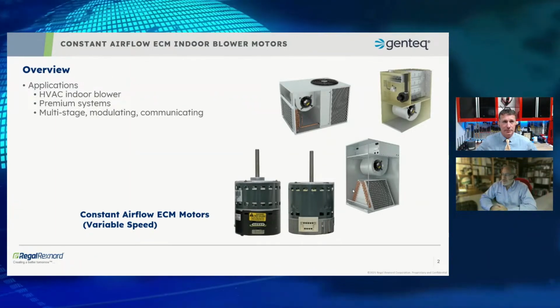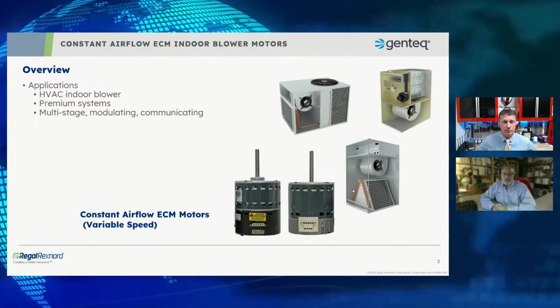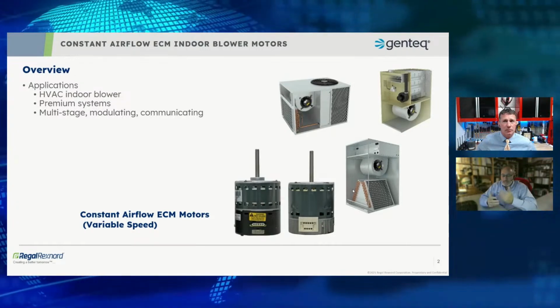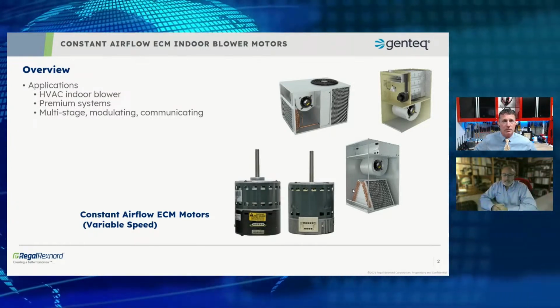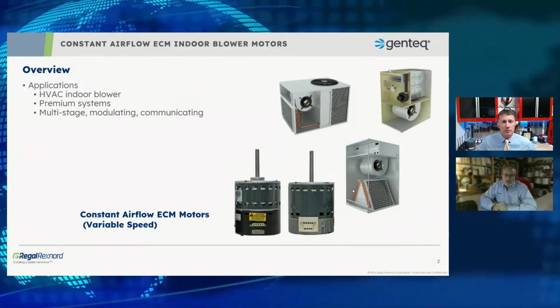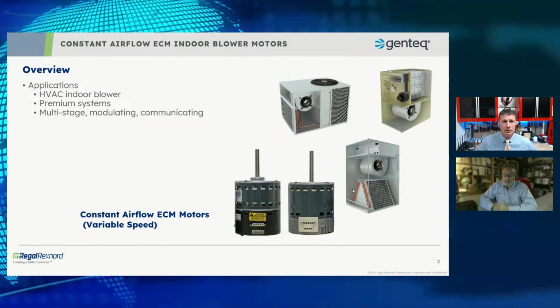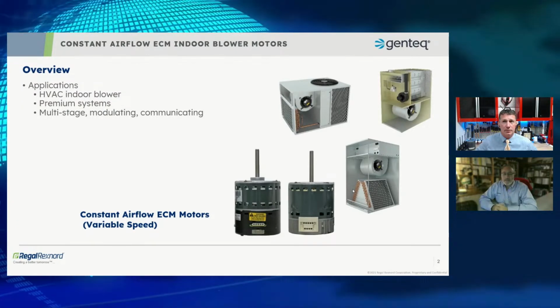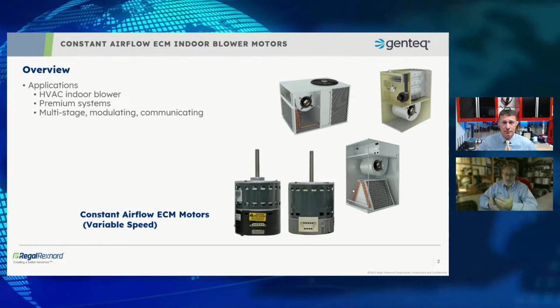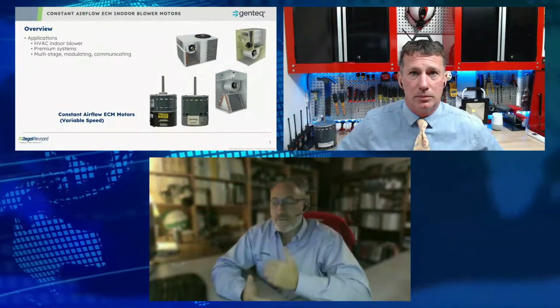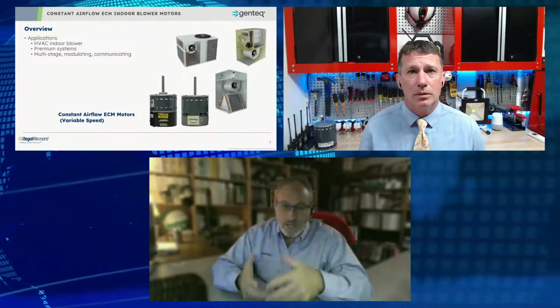Oh, absolutely. So the reason I like the term that our engineers gave this motor way back when, constant airflow, is if you really just focus on the words, it's a constant airflow motor. It's kind of like if you focus on the words cruise control on your car. When I set the cruise control, it maintains 70 miles an hour. When I have a constant airflow motor, I might be maintaining airflow, and that's exactly what the motor does. So you kind of get a better understanding of what the motor does when you listen to the words constant airflow, constant torque, constant speed. And so we'll start off with the constant airflow motor in this session, as you said.